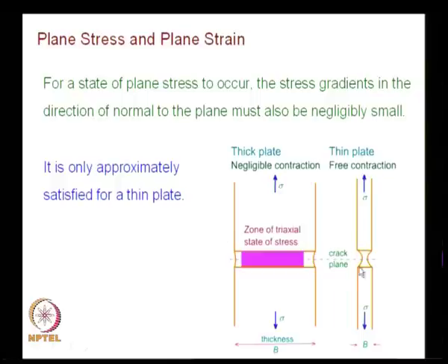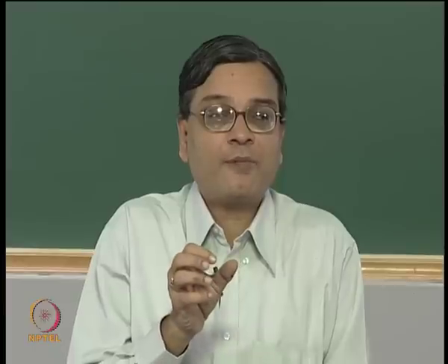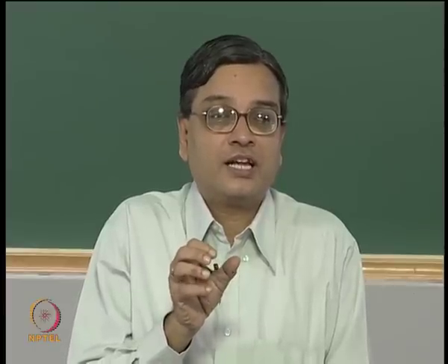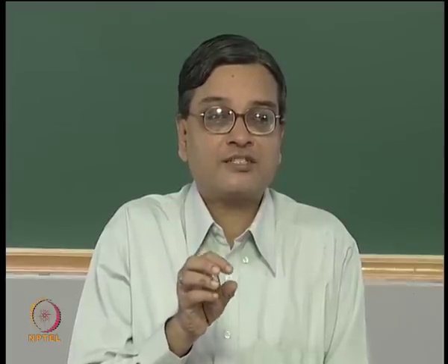See, because of plastic deformation, the neighboring elastic region will refuse to deform to that extent. So, you will have sort of tension compression type of situation in the plastic zone as well as the elastic zone.